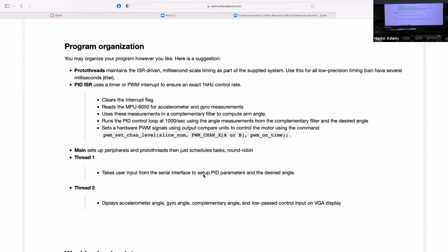One way that you might consider setting up your program is to have a single interrupt service routine that is connected to the PWM channel. Connected more specifically to the PWM slice, which has 2 output channels, right? So I'll just remind you that we are using these 2 PWM outputs to control an H-bridge. That H-bridge, that's another thing that I want to remind folks of. So we'll look at that in more detail in a moment.